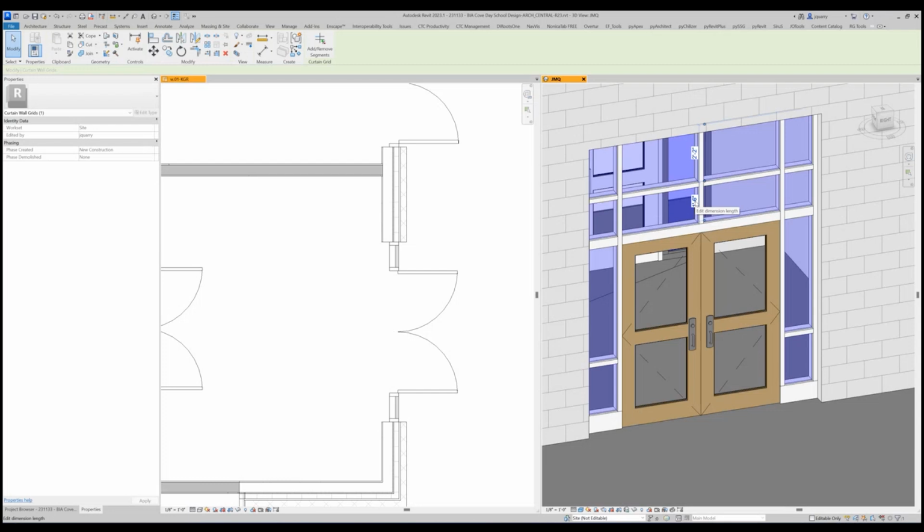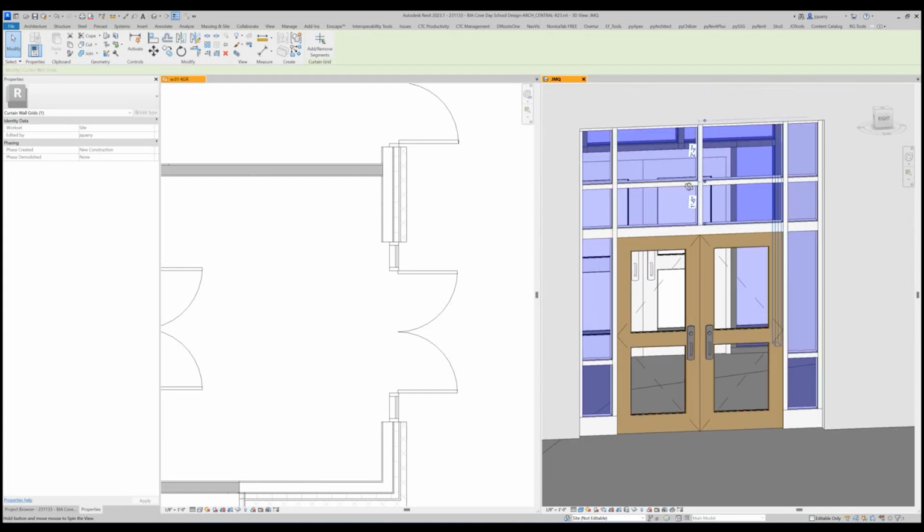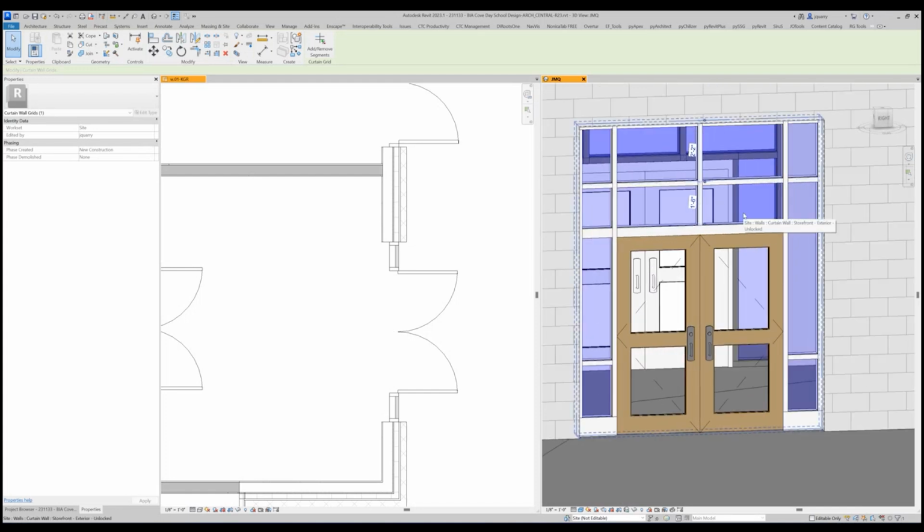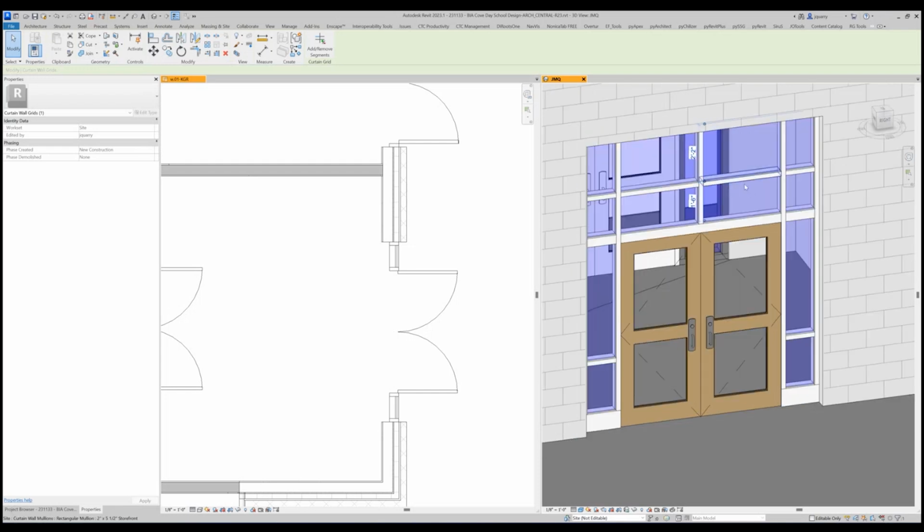I am looking for anything that aligns with those heights. So, yeah, on that door schedule, I'm going to look at that too. Yeah, I've got it pulled up. So I'm just looking at if there's anything that's at 12'6", which isn't a coursing dimension. So I would think it would need to be at 12'8".